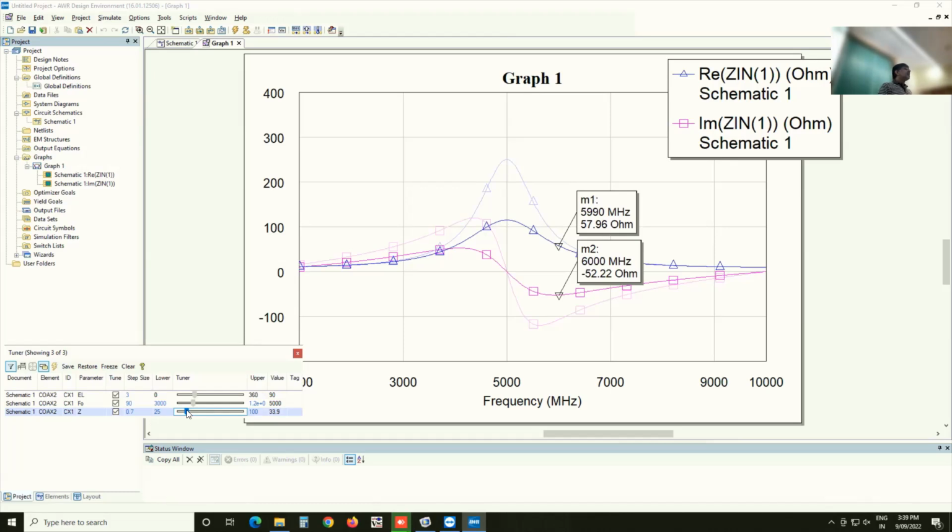Which means it's sort of working over a larger range of frequencies. A natural figure of merit for such a circuit: if I'm trying to match something to 10 ohms, then as long as it's within a few percent of that 10 ohms, I will call it matched. If the curve becomes flatter, it's working over a broader range of frequency. So, you were asking about the bandwidth: for a single 90 degree section, which is basically the quarter wave transformer, it depends on how different an impedance you're trying to match.